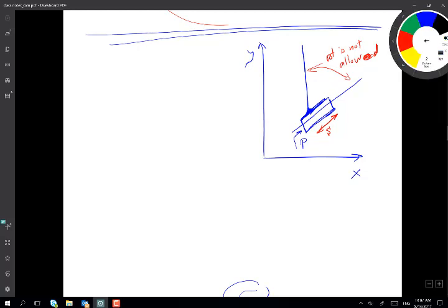This link here has 3 degrees of freedom: x, y, and the angle theta. Then for any point on the other link, I need to know the distance, because the angle between them is fixed. So I need to know S. So the degrees of freedom here are x, y, theta, and S, equal to 4.